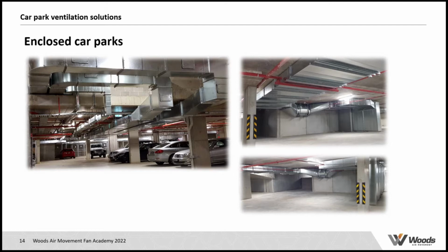Apart from the fact that it's difficult to get the space for the ductwork itself, you get quite awkwardly sized ductwork, which often turns into a lot of resistance, which turns into larger fan motors, which turns into more money to operate the car park, because it will take more energy to move that air through the duct.